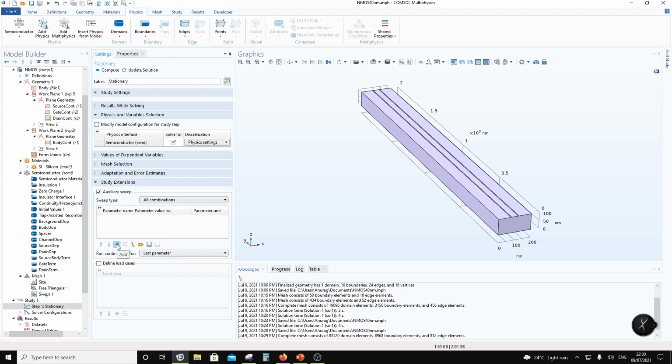First thing I'm going to add is VD, because I want to plot the transfer characteristics to find out the threshold voltage. From the transfer characteristics, I'm going to get the following information. I'm going to get the sub-threshold leakage. I'm going to get the sub-threshold slope. I'm going to get the threshold voltage. I'm going to get the trans-conductance. I'm going to get the mobility degradation.